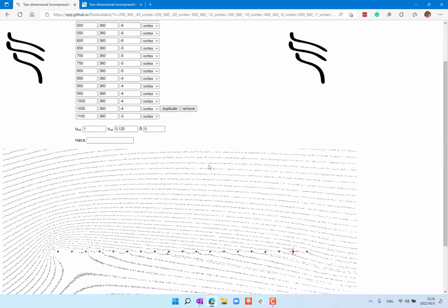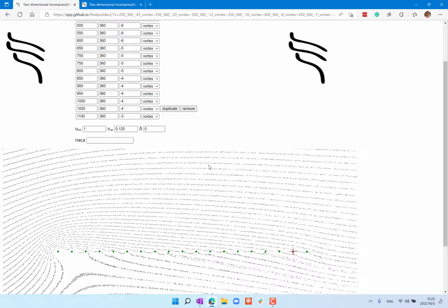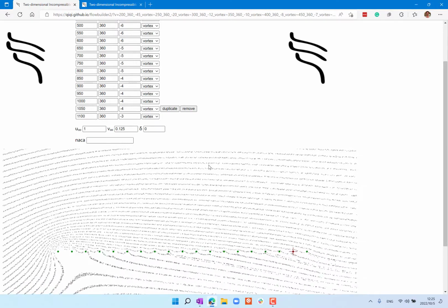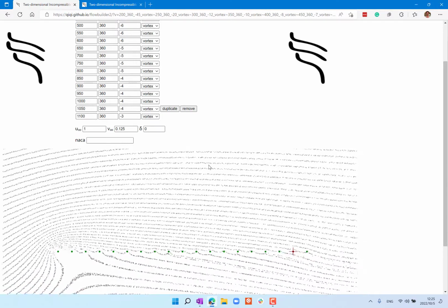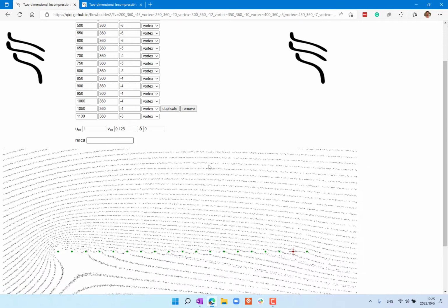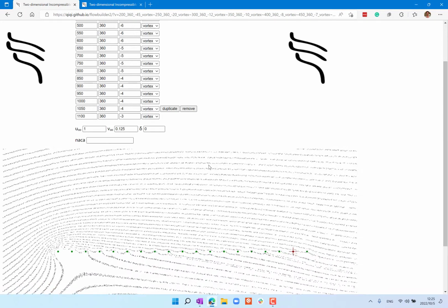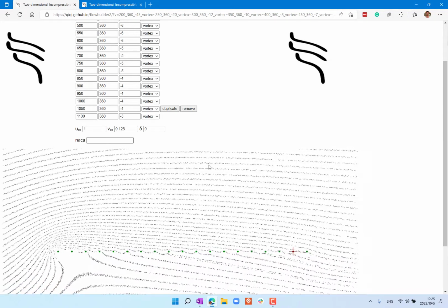if you put it at an angle of attack, you get a lift distribution that is exactly that function, and the lift is going to be at the quarter chord. Not only that, but also for asymmetric airfoils, the lift will not be at the quarter chord. We are going to be discussing it next week.